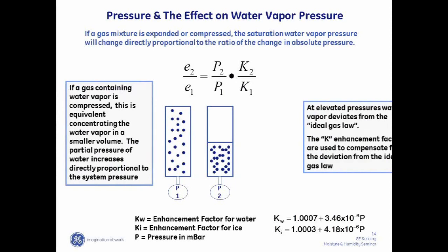Our technologies can also be used to measure moisture in organic liquids, for example, in hydrocarbons such as oils or hexane or even refrigerants. The key is that we can only measure in non-miscible liquids. So, for example, somebody once asked me if I could measure the dryness of a martini with our sensor, and unfortunately you can't, because that's a miscible liquid. Alcohol, the gin or vodka, mixes completely with water, so that would be a miscible liquid. We can only measure in non-miscible liquids.